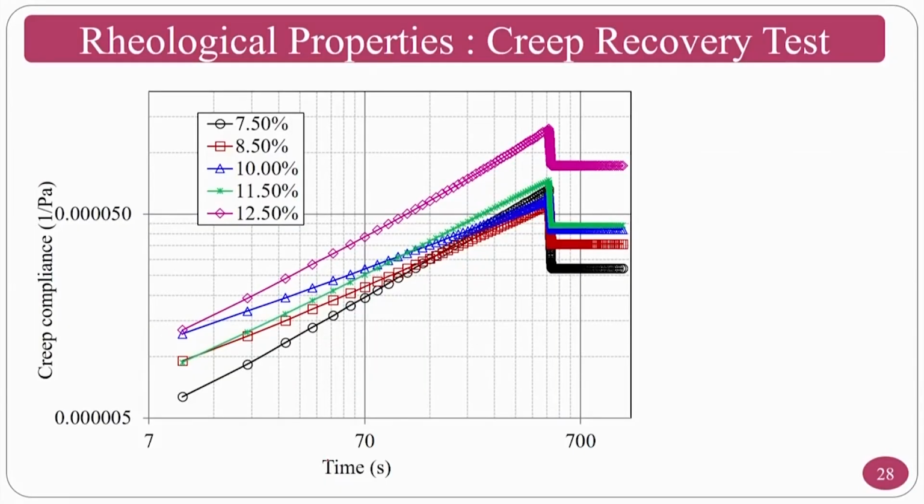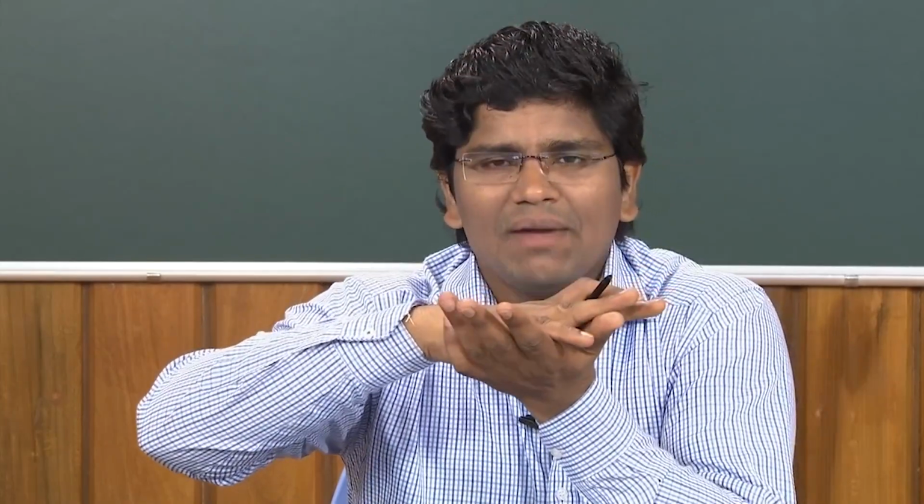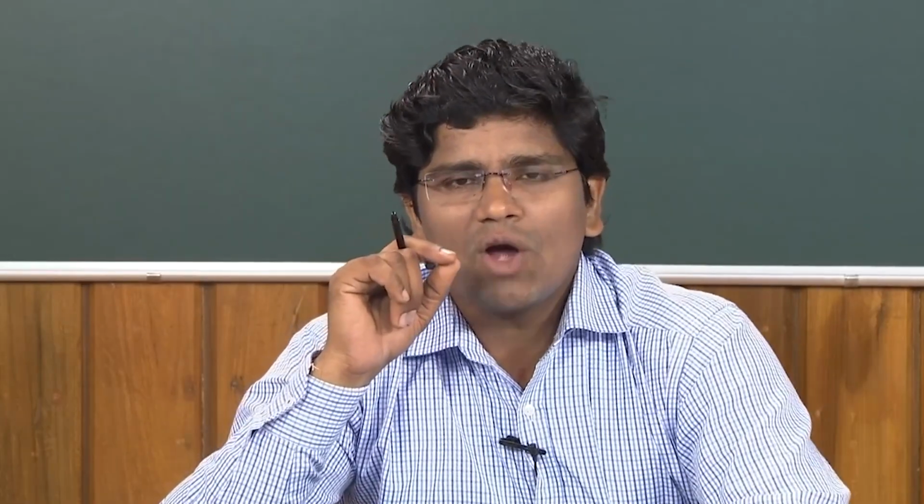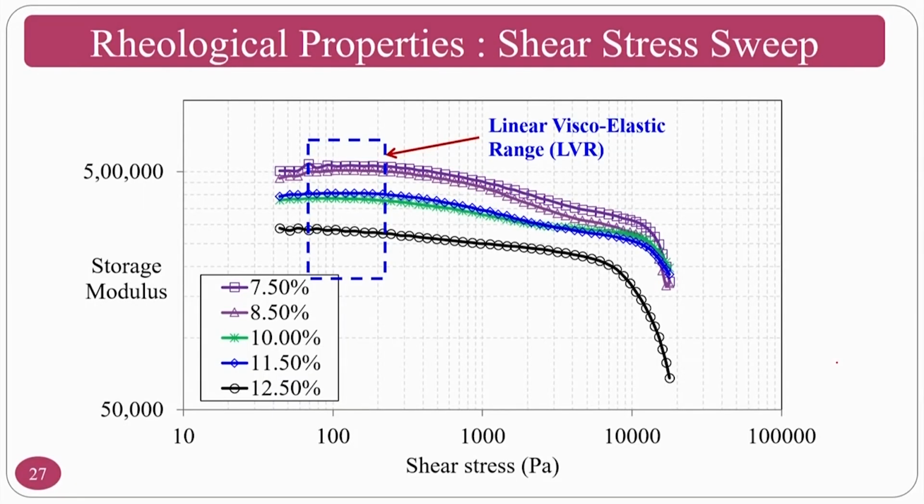Okay. So, creep means a certain load you are applying and holding for some time and you are observing the strain. Since the stress, or the load, is constant, the strain will continuously change with respect to time, and you want to observe the strain. Okay. That is what is done in this particular test. The basic problem in this curve is how much load one has to apply. For that purpose, people have to do the shear stress sweep curve.